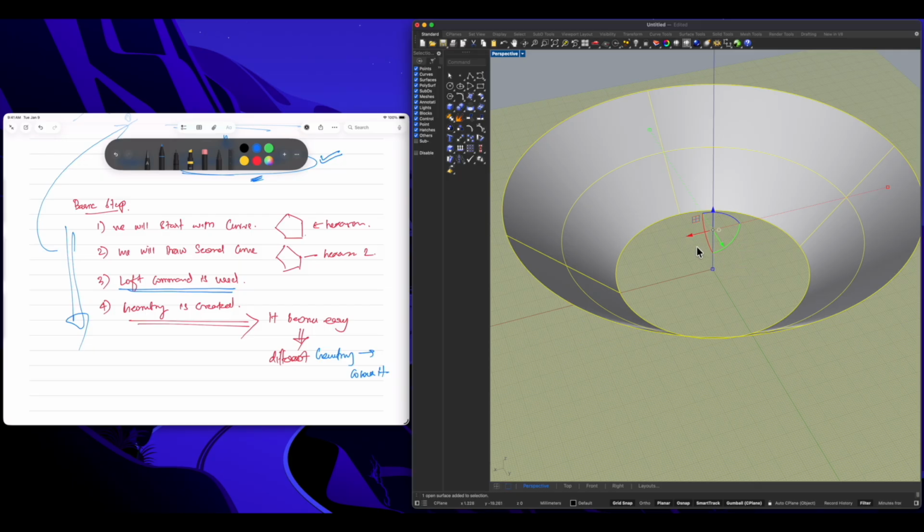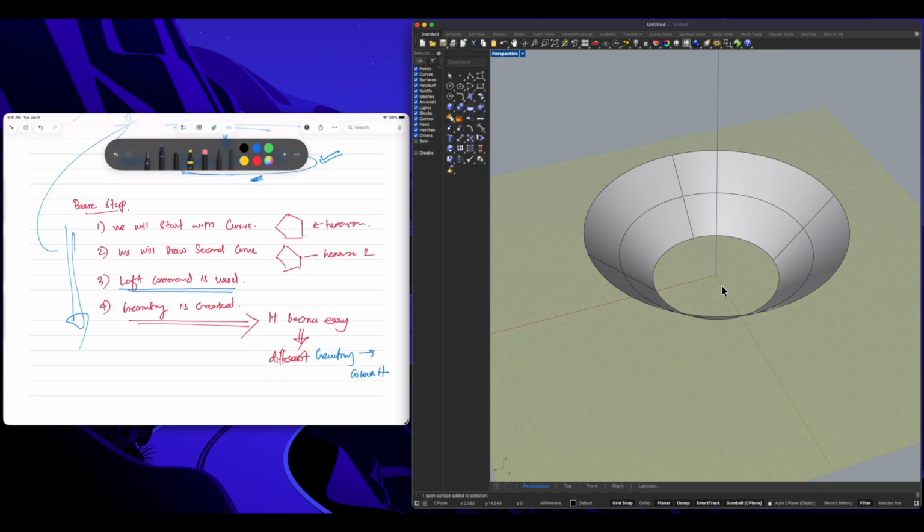Move Gumball. So what I am going to do is copy this geometry one by one. To copy this, you need to press the shift key. Shift key plus option key is used to scale it in 3D, and in order to scale you need to press this square.